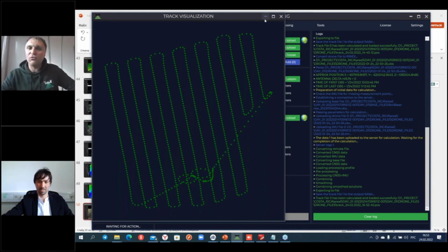Do you have another question for me? We have another one which is directly connected. What is the best altitude for the 200 Ultra LiDAR? The working altitude for the 200 Ultra LiDAR starts from 50 meters up to 150 meters. You can work in the whole range of altitudes from 50 meters up to 150 meters.